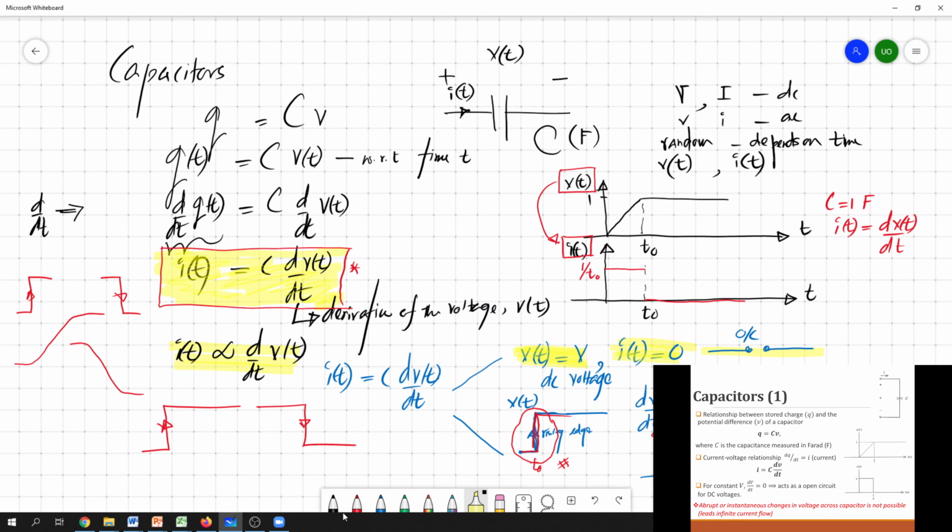So then there won't be any capacitor in the circuit. It is an open circuit element once you apply a DC voltage. If you have sharp rising or falling edges, the derivative becomes infinite and you will see an infinite current. In a practical circuit, at the given point, if you have a rising or falling edge, the current simply goes to its maximum, which we can draw from the external source.